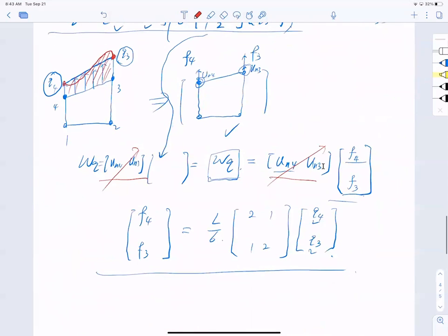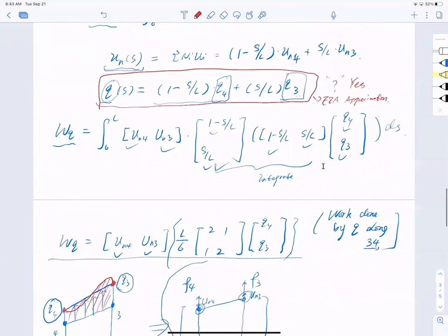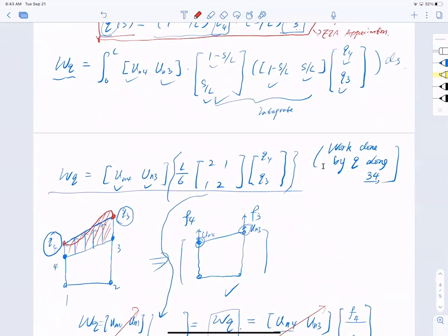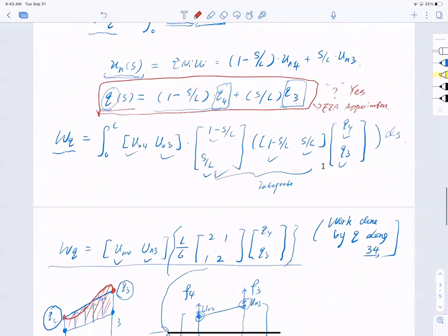The discretization of traction, or conversion of traction along the sides into nodal value, does not depend on the shape of the real distribution of the stresses. It only depends on what? The shape function of the element. Very important.